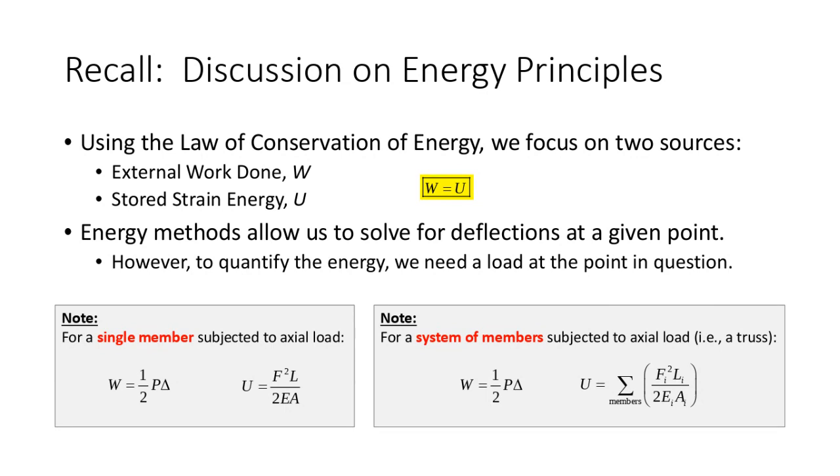The deflection is 0. Okay, and so if you have a 3x3 system of equations, sum of forces in the x direction, sum of forces in the y direction, sum of moments, that's 3 equations, 3 unknowns. If I throw another roller in there, that makes it indeterminate. But how do I solve that indeterminate structure? I can recognize that the deflection at that roller is 0. But I can't use that if I don't understand how to compute deflection.